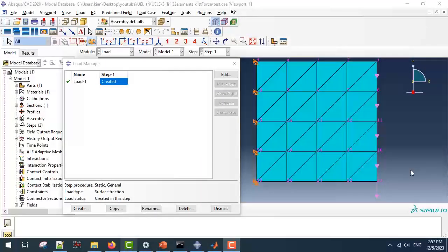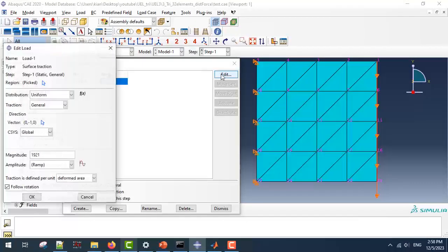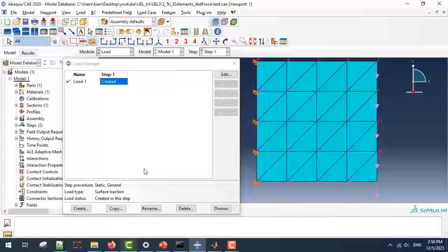In the following example, we are going to use a distributed load instead of point loads. As you can see here, the distributed load is a shear load with an odd number amount, since I don't want to have any chance of being lucky for the distribution. So if you have paid attention, I did not construct a force vector for external loads in the previous example, since Abaqus automatically transfers the point loads to the global force. Now we are going to exploit that option.